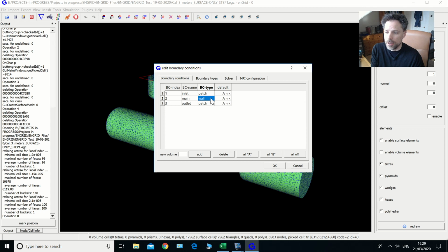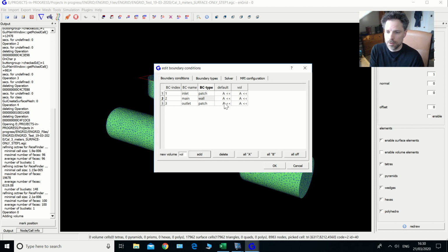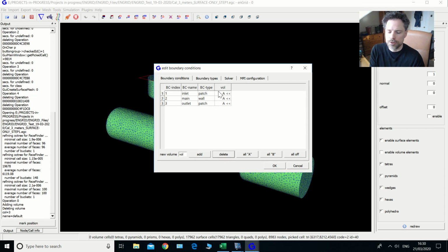And we also want these to define an internal volume, because these are just 2D. No, they're not three-dimensional, are they, in terms of thickness? So we're going to add a new volume. So just type volume add, and I'm going to delete that one. So this basically just means these 3 patches are going to define the internal volume, and each of them is just defining which face direction is closing off that volume. So normally that sort of works out to be okay.